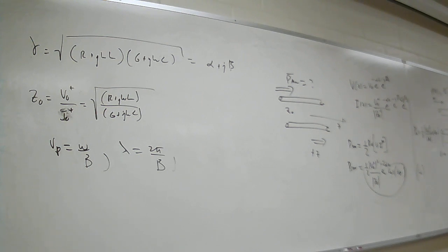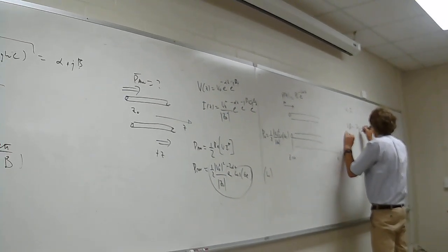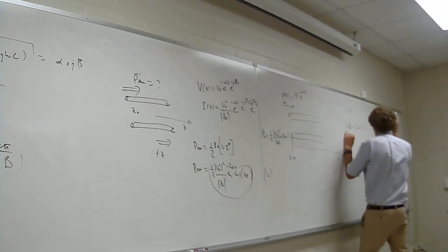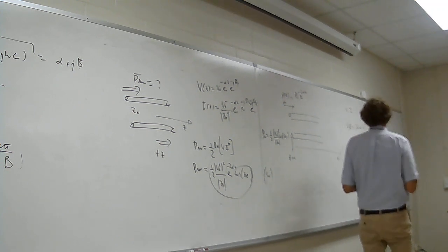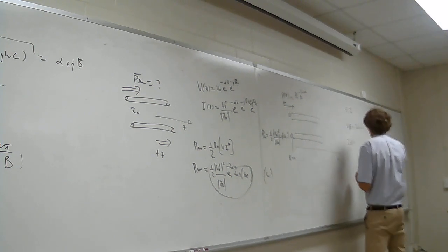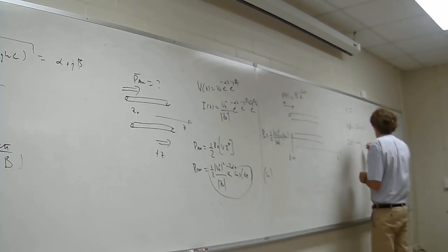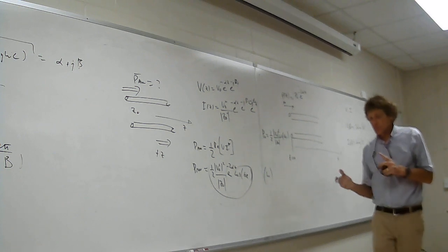if you're talking about voltage or current, write this down if you don't know it. And you want the decibel value. If you want V in dB or decibels, that's 20 times the log of V, period. And I'll give you an example of this. So you use a 20 there. If you want the current in a decibel value, it would be 20 times the log of the magnitude of the current. Now this is just generally true for voltage or current.